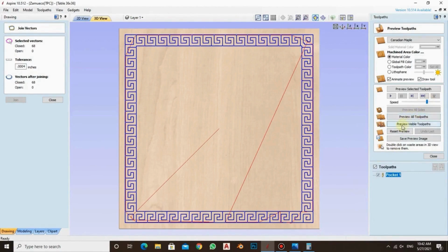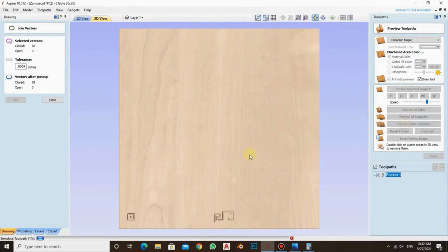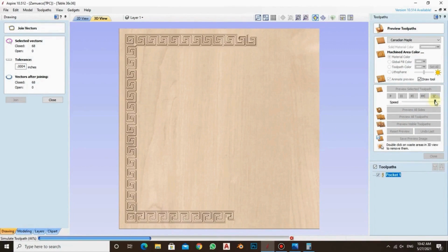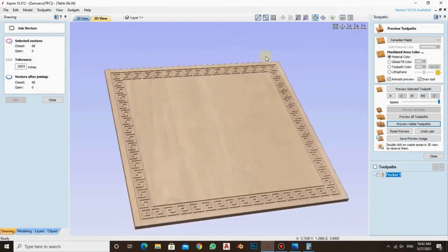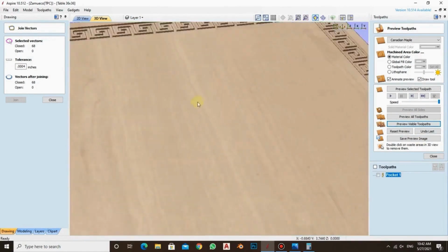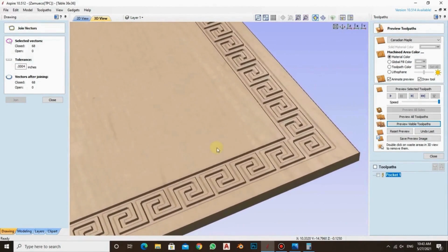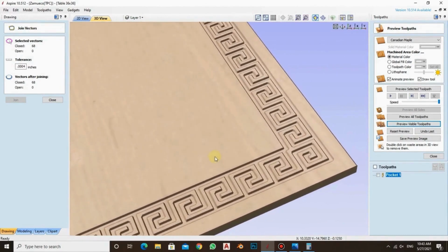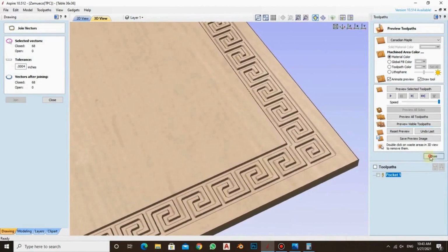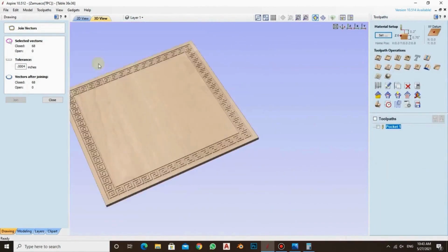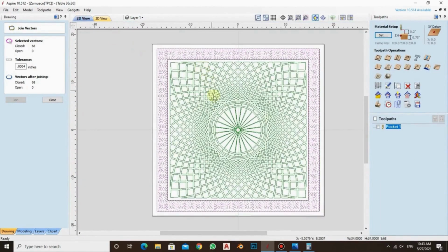As soon as we go to the selector, we've already set the design and closed objects. Close it, calculate. Let's preview. I'll slow down the preview speed a bit. I'll make the tool path visible in the preview. So look at this tool. It's creatively viewing it in orbital mode. It's cut it very nicely. After this cutting, we'll exit.